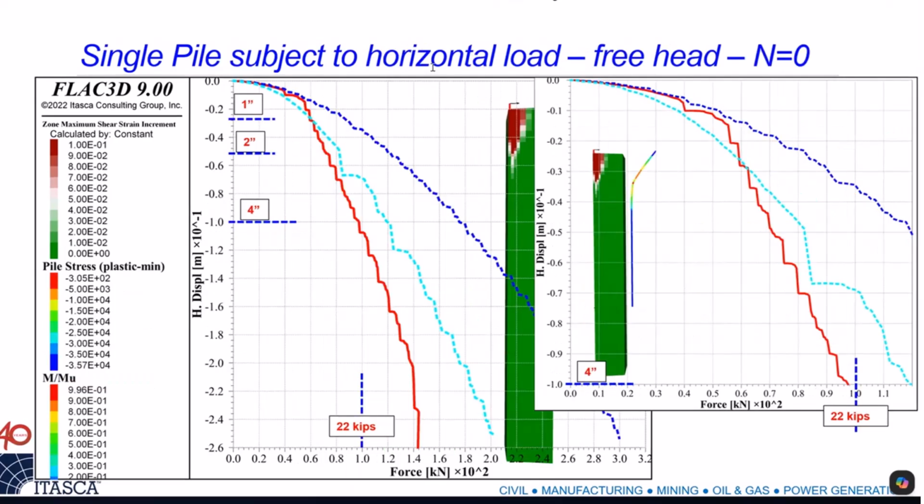Now, let's go into the lateral deformation. This is for zero axial force. But what you actually see is that at the end of the day, once you accommodate the nonlinear behavior of the structure, even if you have a soft soil, the coupling springs are essentially marginal because you have a failure of the pile because of plastic hinges. There is this idea that it is always the soil failing, or that the stiffness of the pile somehow doesn't matter. But I can guarantee you, having seen load tests with inclinometers inside the pile, the cracking of the pile itself really changes the load transfer curve in the horizontal direction, especially because of the cracking of the concrete and the change in stiffness of the concrete itself.